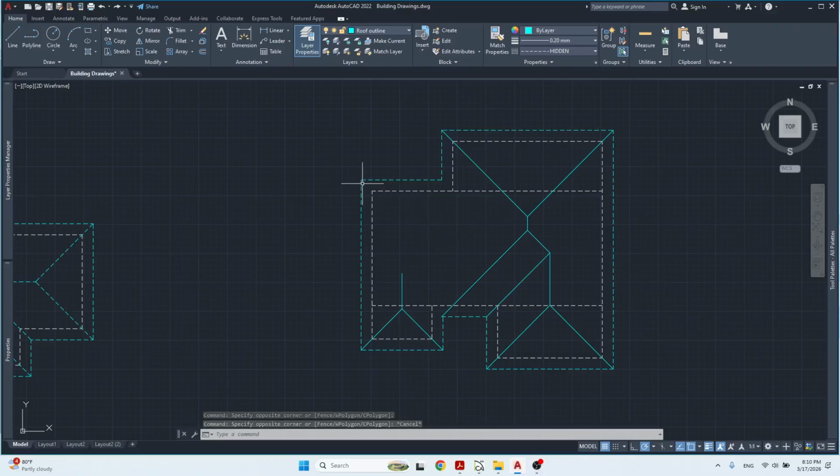Okay, so if this is a rectangle, that means it would have its own edge running somewhere around here, and then it would have its hip rafters running in from here, also from the other corner that would be somewhere around here. In order to know that, we need to extend our overhang lines.